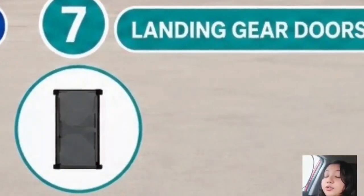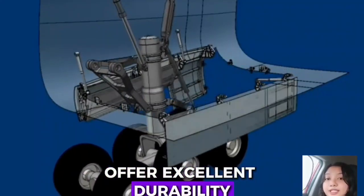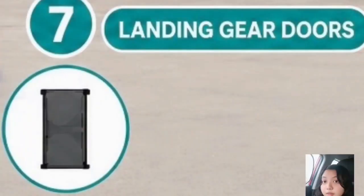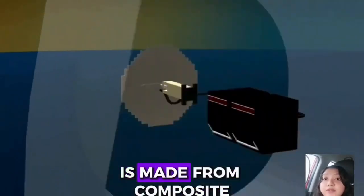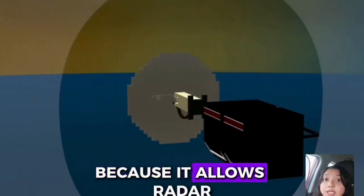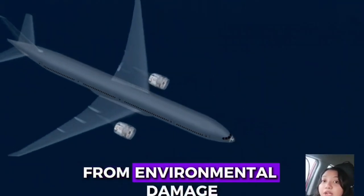The landing gear doors also use composite materials. They are lighter and offer excellent durability and impact resistance. Finally, the radome, which covers the radar system, is made from composite because it allows radar signals to pass through while protecting the equipment from environmental damage.